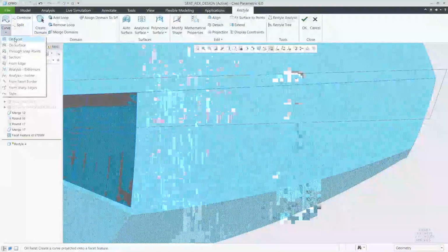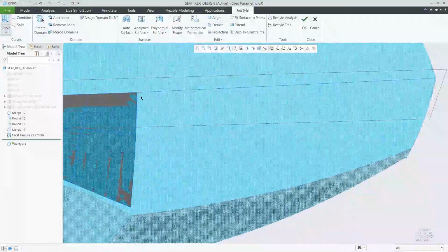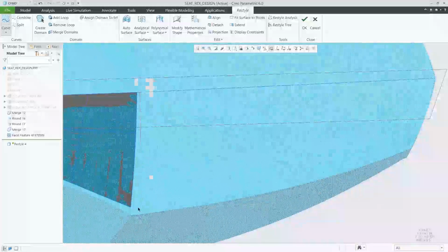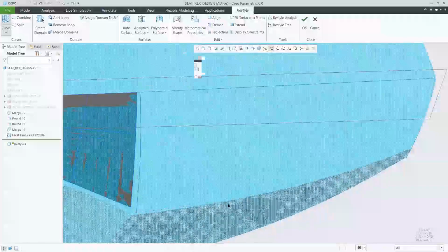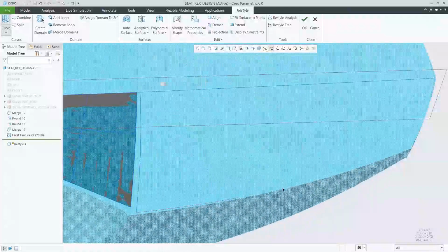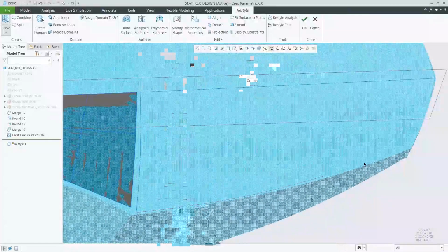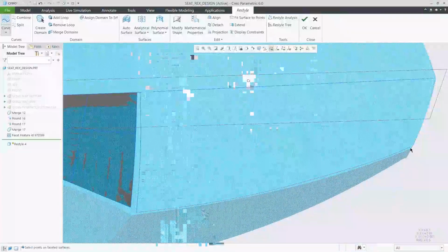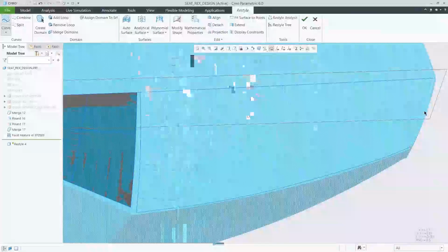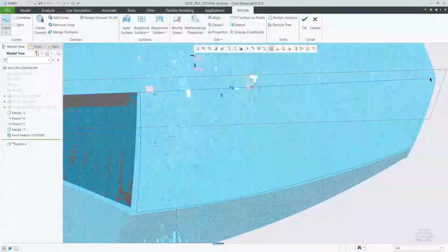And now we're going to go right along the outside of that section that we want to place our next surface down. And what you'll notice as I'm going through and doing this is I'm leaving a little bit of distance between my curve and the outer side edge of that geometry. And that's because I'm going to go through and merge these different sections later on and round off those areas. So in our case, there's no need for us to try to align it up perfectly.